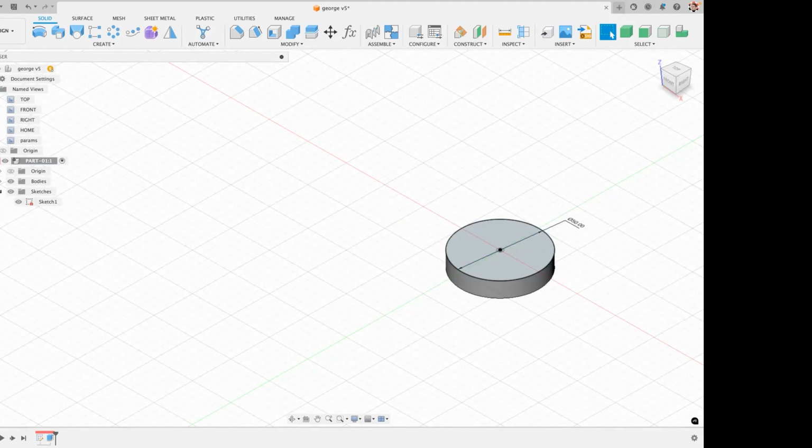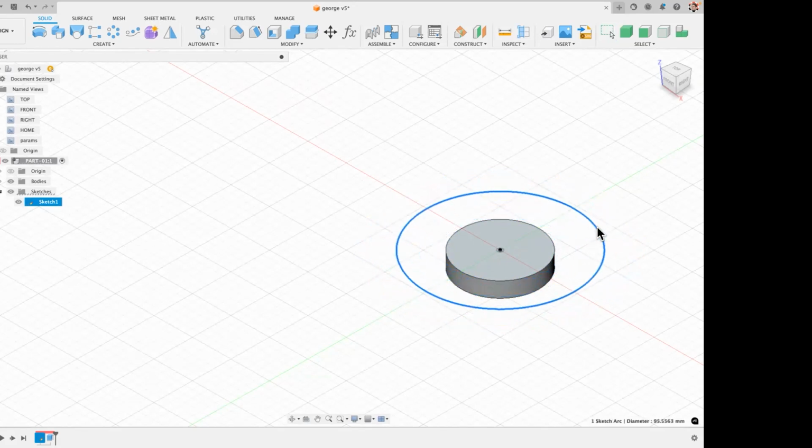So if you've assigned dimensions inside the sketch, when you're outside of the sketch, you can show them and change them and see things change somewhat instantly. If you're in the sketch, you can change them, but you don't see the effect until you get out of the sketch. So this gives you a more interactive, dynamic way of adjusting your model and seeing the changes.